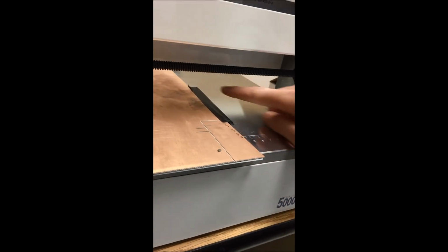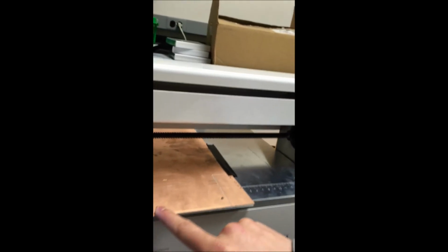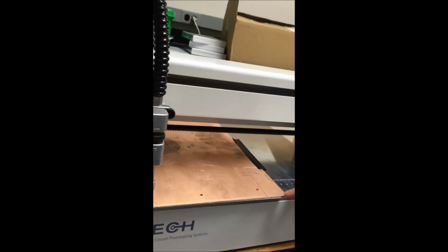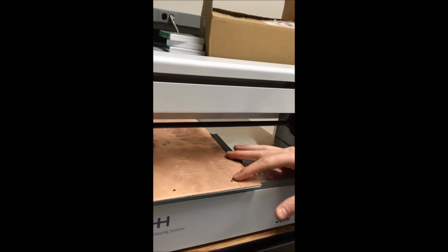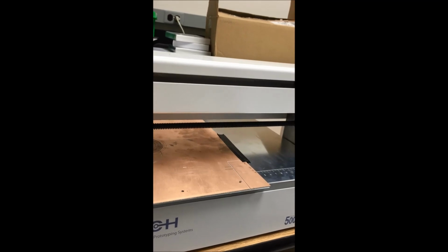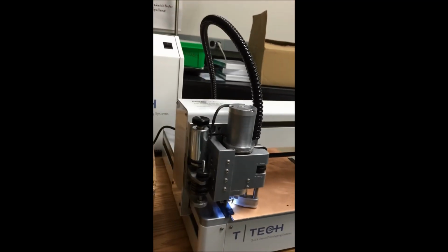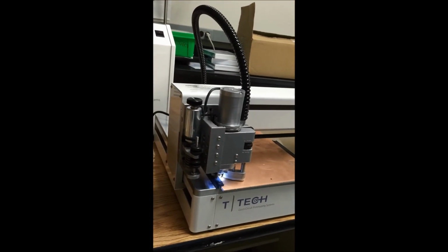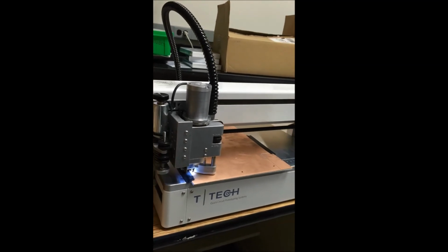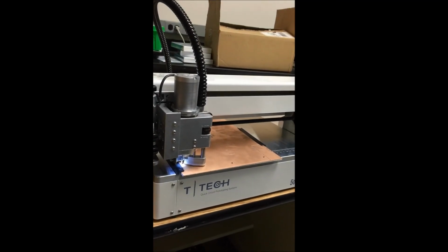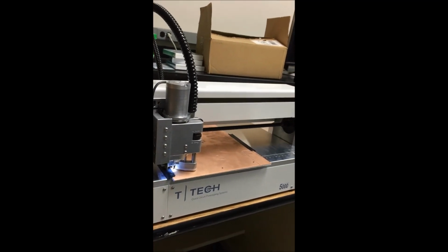That being one of the 2 pins you have to set with an 1/8" drill hole in order to fix the board here. And then I also have 2 pieces of tape on either side. Pin on the far side. The way it's supposed to be done is right in the middle of the board material. The reason I have it on a far side right now is because of the way the home position is mapped. I think in IsoPro it just seems to be kind of offset to one side, so to get the thing up and running, I offset the holes a little bit.